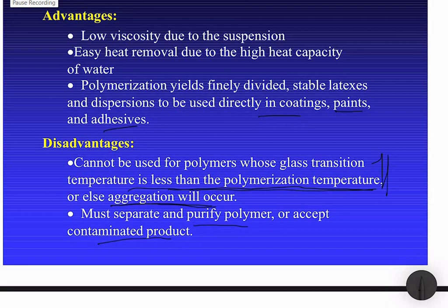And once you get the polymer precipitated, in case you have not viscosified your medium, you must have a proper technique for separation and purification, because you have used a suspending agent and that will be entrapped within the polymer. So you must have a very good separation and purification technique, so that you can remove the suspending agent from the polymer for its application.